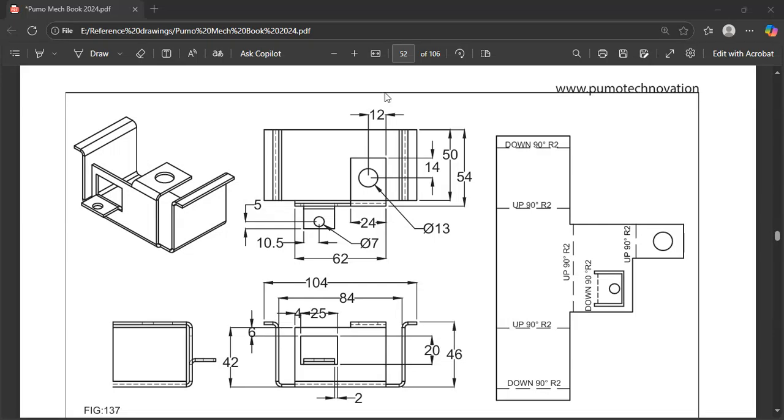Let's do one more exercise from the sheet metal concept in CATIA software. So see, my views are projected here, isometric views there, and this is called the deployment view or flatten view. If you see these orthographic views, you can understand that it is easy to model it from the front view. So for that I'm making this model from the front view.